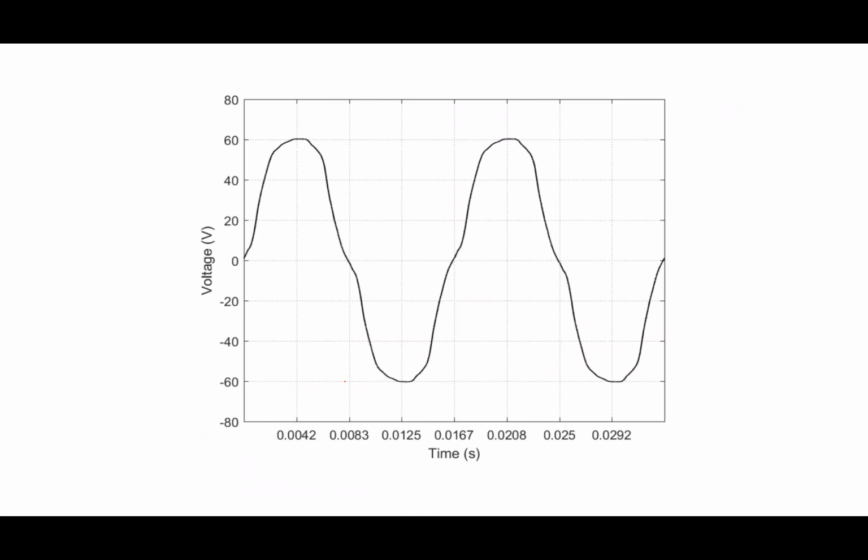Now, somebody said there that the wall voltage should be a 60 hertz sine wave, and it should be, right? This is actually what it looks like in the building here in Epic. It's scaled down so we can safely measure it. It should be about 170 volts peak. But if I look at that, it kind of looks like a sine wave, but kind of not. It looks a little chopped off, a little flat at the top, and it's got those little shoulders that have developed near the zero crossings. If I look at that, what I find is that this thing is periodic, so it's got a Fourier series.